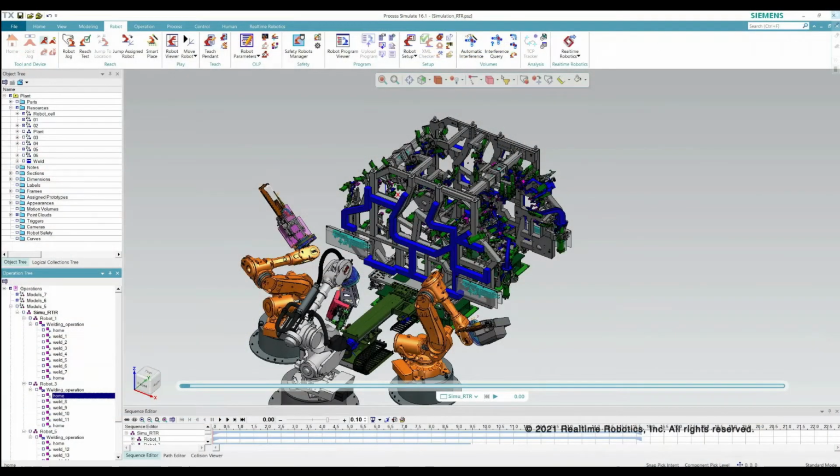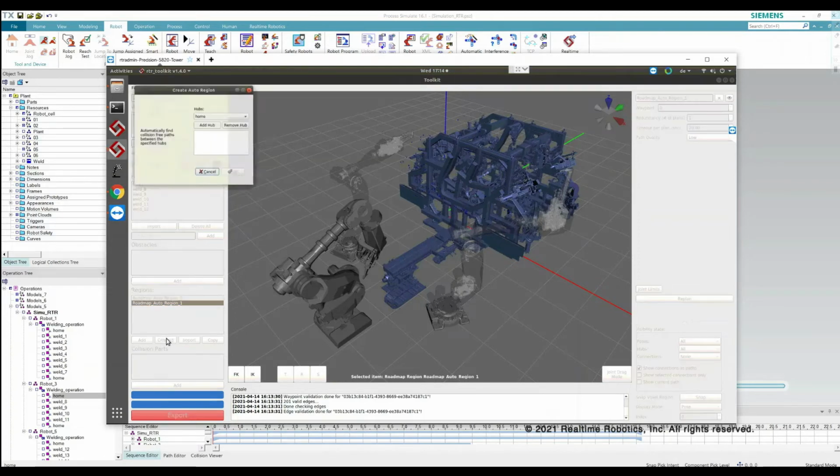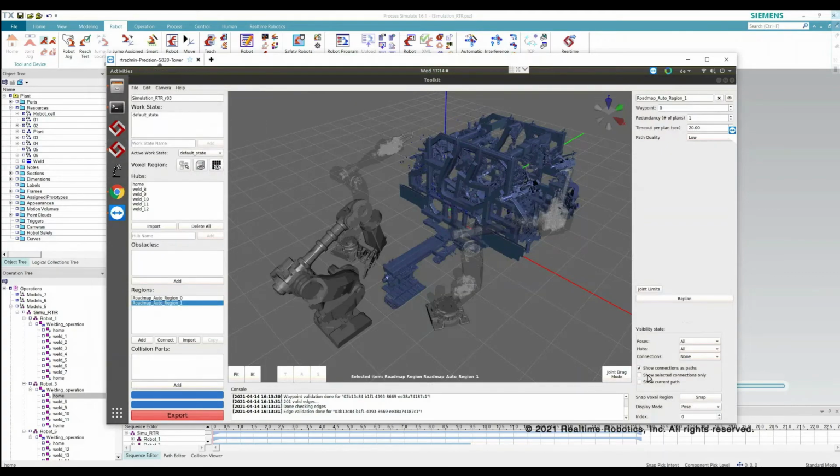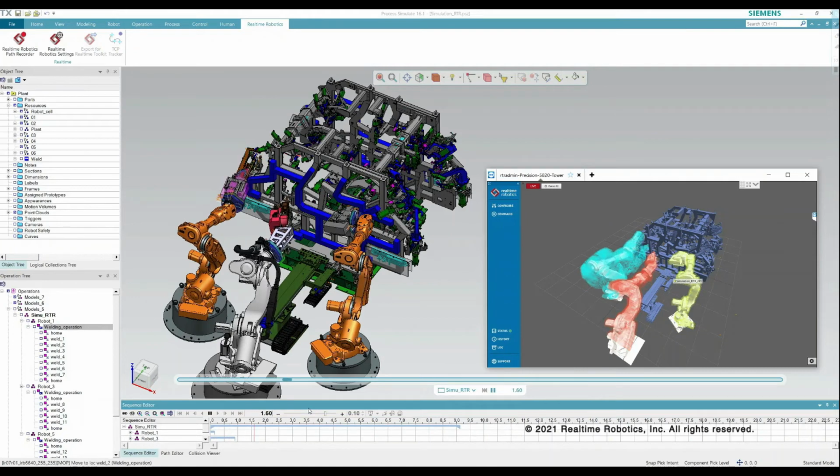One of the nice things about CAD Exchanger is the meshing support it provides. Turning any BREP representation into meshes is important for us for visualization and collision checking and a bunch of other things. And CAD Exchanger provides a really nice API where there's basically just a couple of knobs that let you control how precisely you want to turn an analytic representation of a shape into a numerical one.